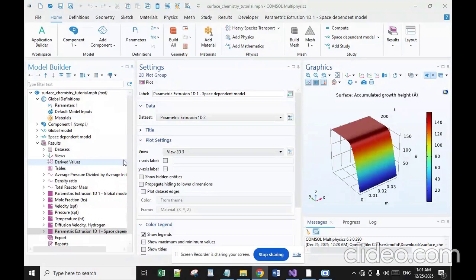And what about the metals? Tungsten CVD, used for forming conductive contacts, wires, and plugs on a semiconductor device, is achieved from tungsten hexafluoride, WF6, which may be deposited in two ways. Other metals, notably aluminum and copper, can be deposited by CVD. However, as of 2010, commercially cost-effective CVD for copper didn't exist, although volatile sources exist, such as Cu(hfac)2. Copper is typically deposited by electroplating.